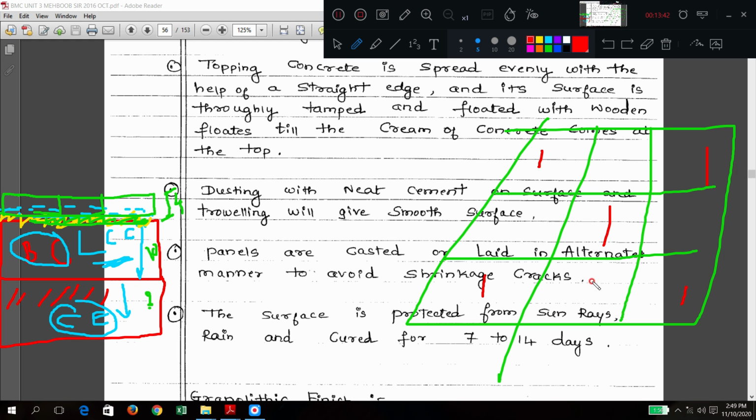Later the gap is there, no, so they go for the second type of panels. Why? During settling also, if any shrinkage is there, the second panel will cover that. If shrinkage is there, means what? Volume reduction. So the second panel will cover for that shrinkage. That is why we call it panel by panel construction.